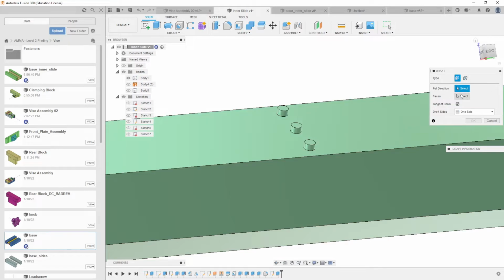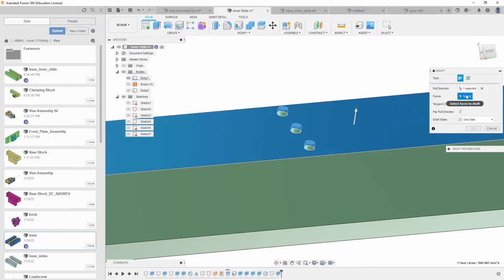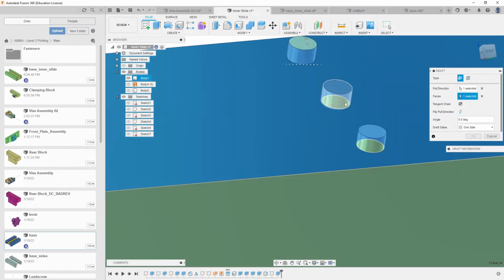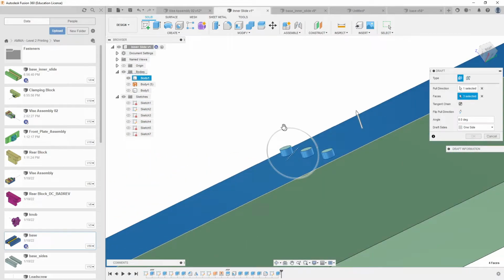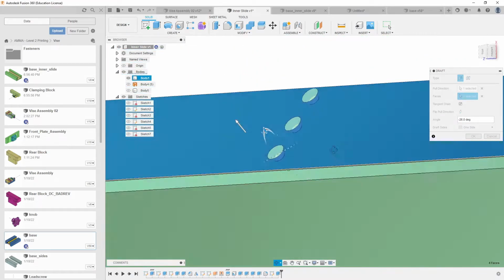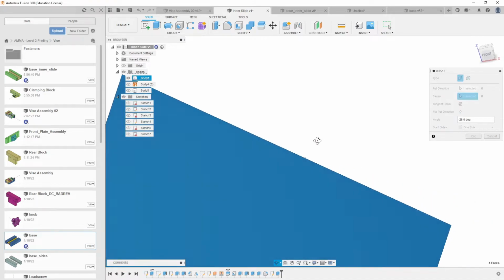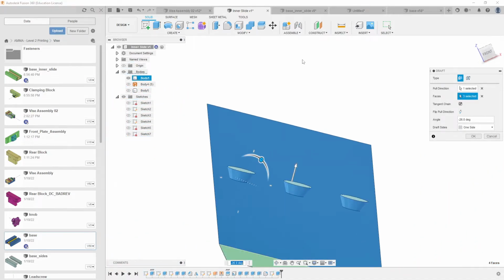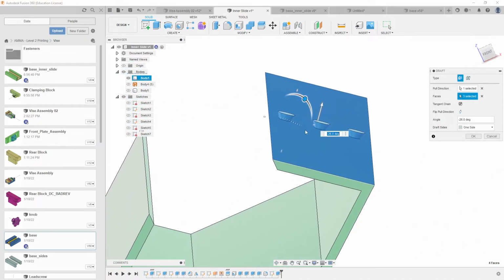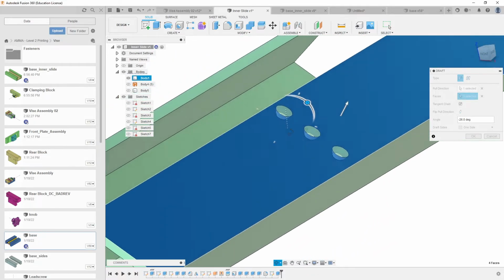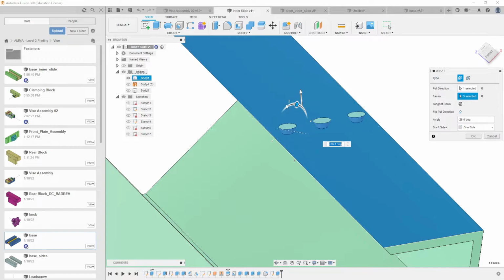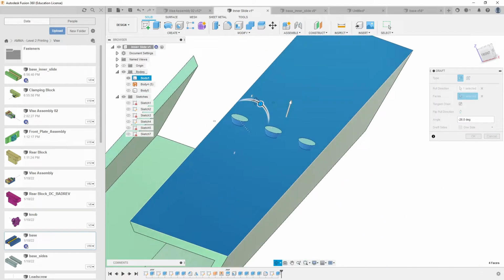Well, in this case, the pulling direction doesn't have to be a part of that feature. I'm going to pick this face, and then the faces are going to be all of these edges right here, and I'm going to pull them out a little bit, you see? Something like this. By the way, if you have trouble rotating, it should pick your rotational center roundabout where you are with your mouse when you go to click.